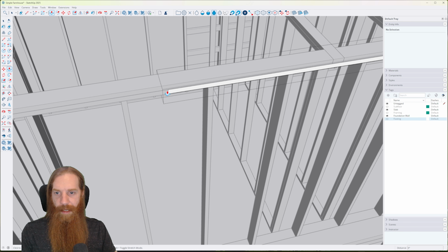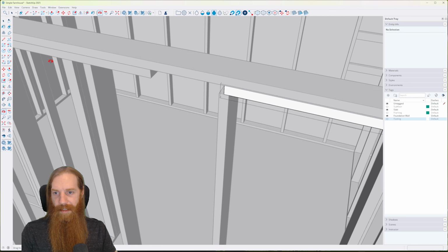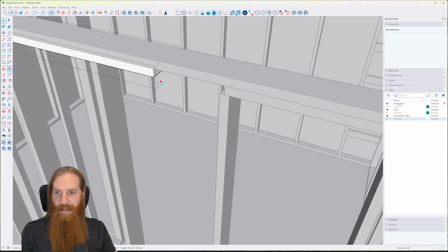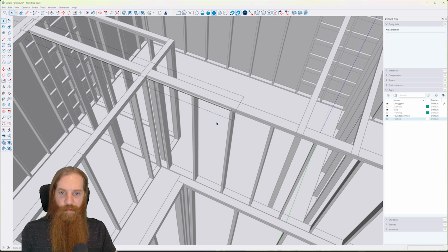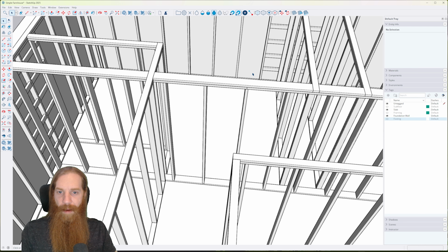When you can't get a 4-foot minimum between seams, I can't seem to grab that. It is okay to go less as long as you're using essentially the max distance that you're able to. This one isn't exactly the max because we are landing it right on the stud, but it's pretty close. Additionally, I should mention, because this is all basement framing, most of it is not structural by any means, so it's not really going to matter where the seams land.